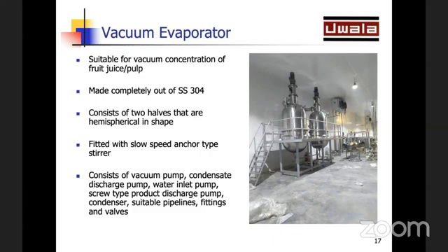The evaporation can be done in various ways. You can either do it in open kettles or in open pans. In open pans, the boiling point is 100 degrees centigrade, which is the normal boiling point of water. So you boil the product at 100 degrees centigrade in order to evaporate the water.